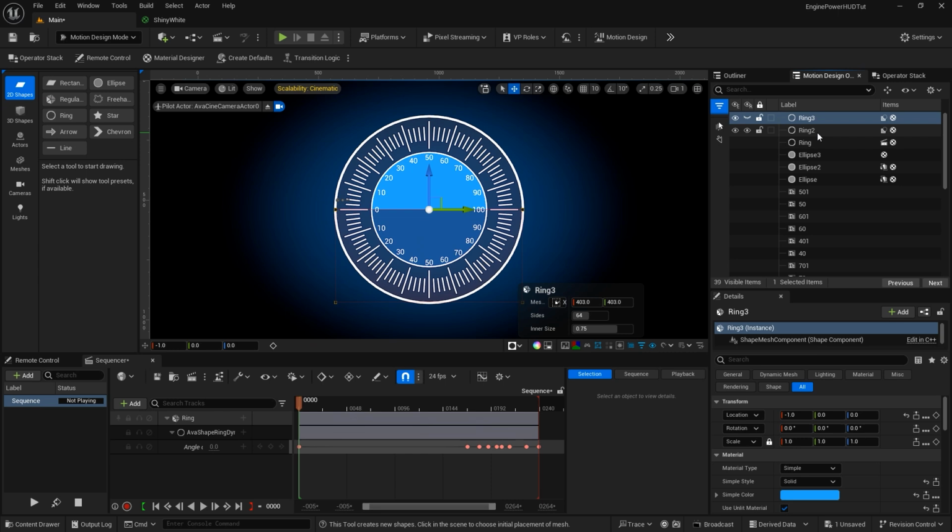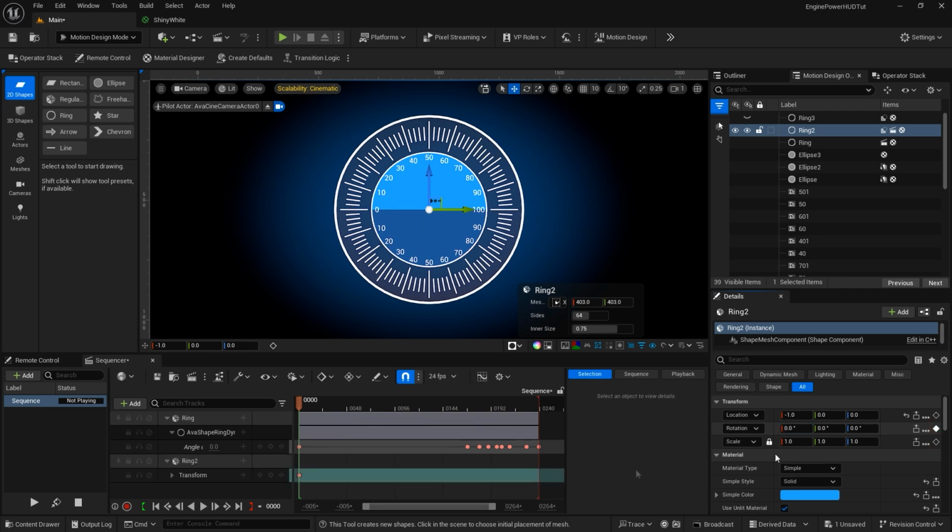And then we will animate ring 2 on the rotation. So I'm just going to select ring 2 to show you this. You'll see that as we rotate it, we're able to move it into place like the other ring. So that's how we're going to animate it. I'm going to set that back to 0. And again, to set this property into the sequencer, I'm going to click the keyframe button right there. It sets ring 2 into the sequencer and the transform property for rotation.